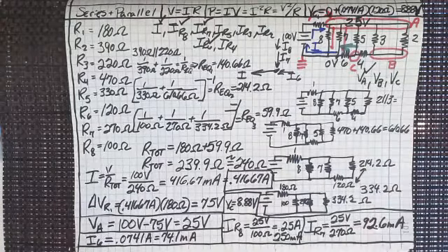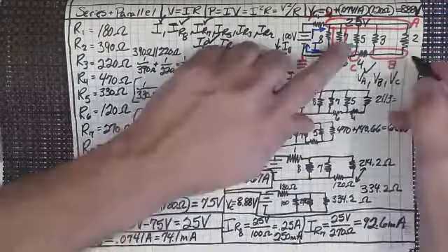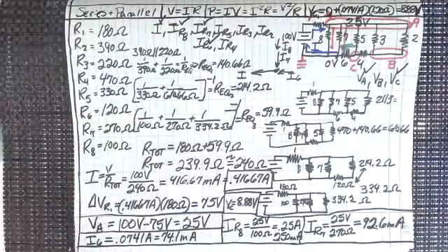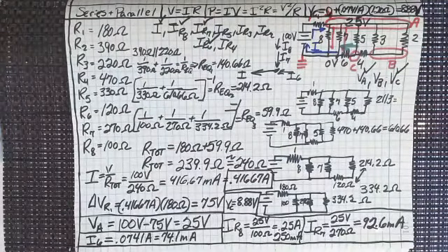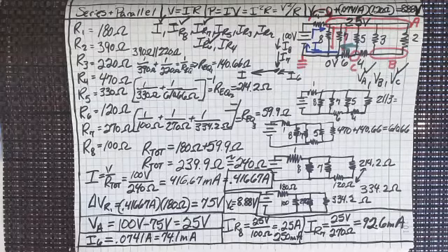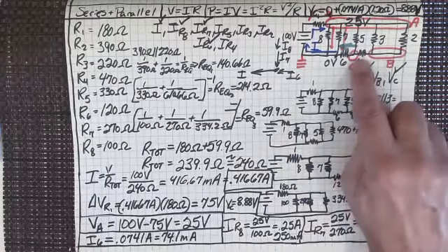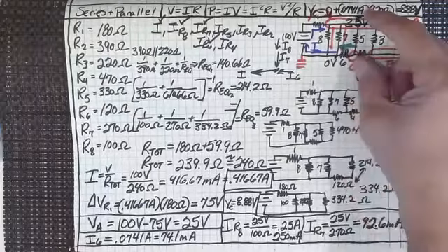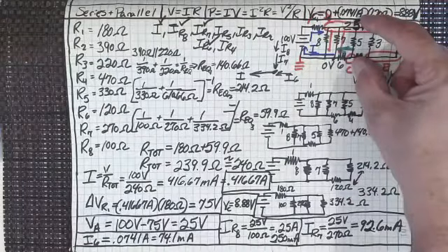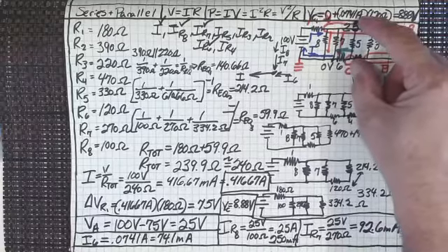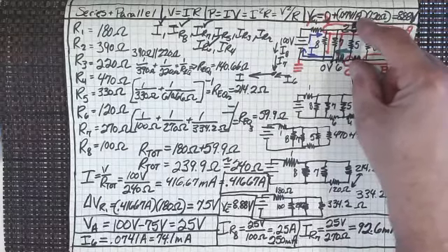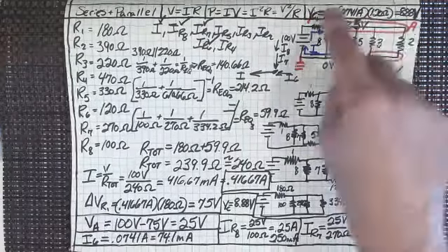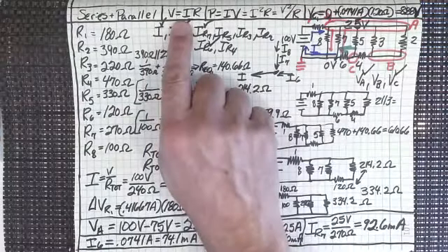We still need, oops, I forgot to mark off V sub C, our last thing that we did there. What else have we got? We don't have 5, 4, 3, or 2. But 5 isn't very far away, is it? Because we now know the voltage at C. We know 25 minus 8.88 is the voltage drop across number 5. So it should be very easy to figure out the current through it. Ohm's law, V equals IR.